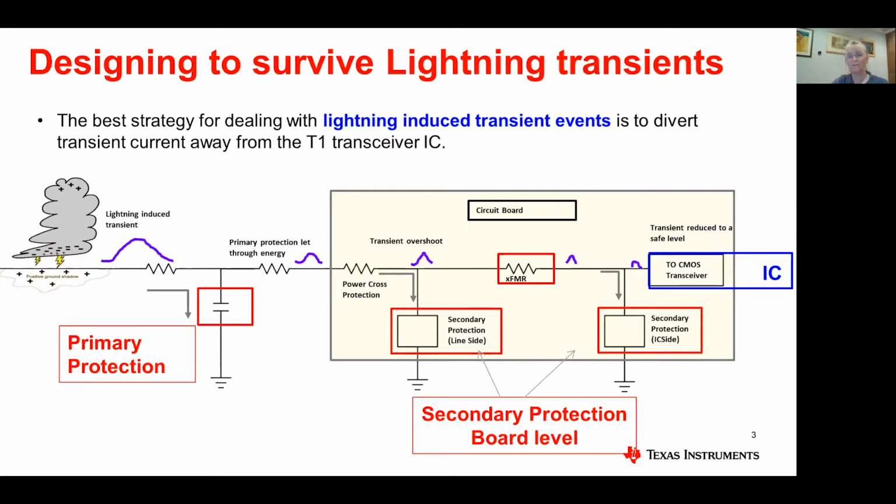Just to give you an idea of the typical magnitudes of voltage and current: in an average electrical storm discharge to ground, the voltage levels will exceed a megavolt, the current levels will exceed tens of kiloamperes, and the discharge time is in the hundreds of milliseconds. Needless to say, this can be very destructive.